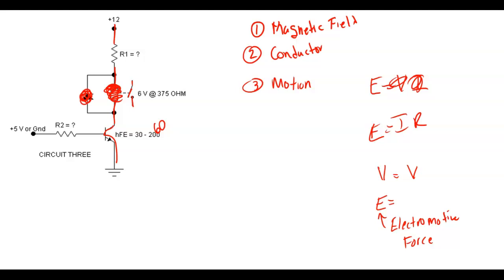Well, you know, transistors and devices can only block so much voltage. So you've got all that voltage giving you all that push. If you go out and buy a wall switch, it's going to be rated at two things. It's going to be rated at a voltage, and it's going to be rated at a current. Well, why do they rate it at a voltage? It's nothing but a switch. Well, that's the amount of voltage they guarantee that switch will be able to block when you open it up.